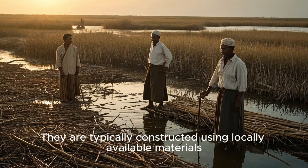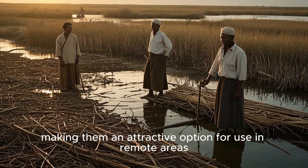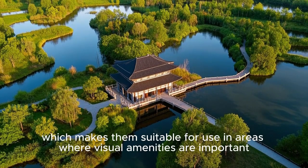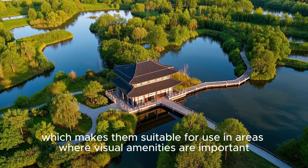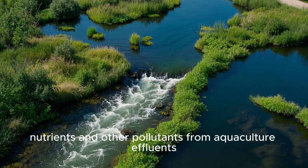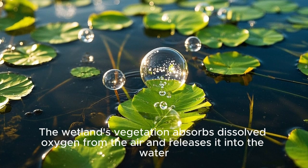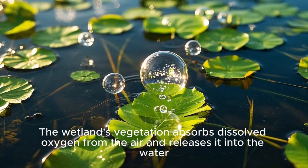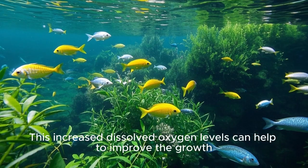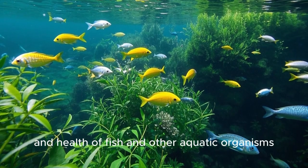The free water surface constructed wetlands are simple to build and therefore usually have low construction costs. They are typically constructed using locally available materials, making them an attractive option for use in remote areas. They also have an aesthetic appeal and can enhance the landscape, which makes them suitable for use in areas where visual amenities are important. Now, the free water surface constructed wetlands are effective at removing organic matter, nutrients, and other pollutants from aquaculture effluents. The wetland's vegetation absorbs oxygen from the air and releases it into the water, which helps to increase the amount of dissolved oxygen available for aquatic life. This increased dissolved oxygen can help to improve the growth and health of fish and other aquatic organisms.